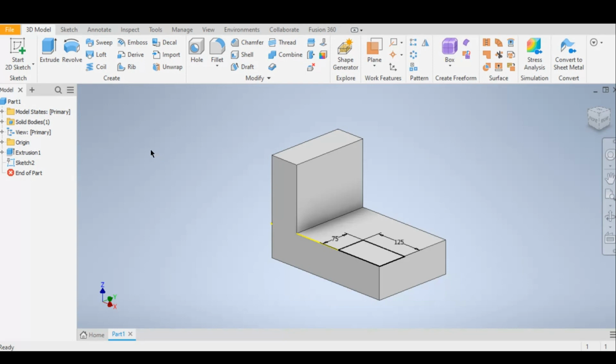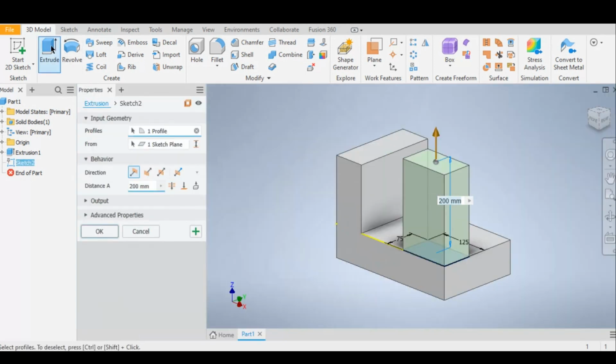To do that, I am going to use the extrude function again. So once you select the extrude function, we'll see this pop up here, and it has our distance that we originally had going here. But to get this, we can enter, let's do just an example to show you guys. You can do a 50 millimeters there. So you can see this is not a subtraction. You can see this is actually just joining to our original sketch, but this is also possible.